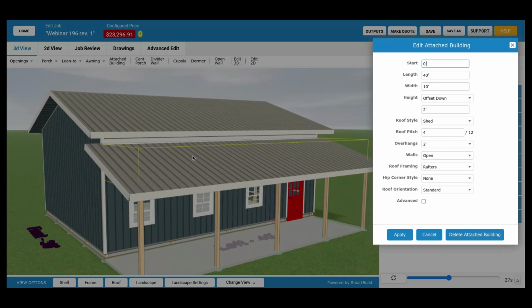because you could potentially have a non-vented gable, right, where you don't hold the sheathing back, so there you'd have an offset of 0, or eave, ridge cap, non-vented ridge cap. But if I use a vented ridge cap, if I use this vented ridge cap, I need it to be held back 2 inches. If I use this other vented ridge cap, I need it held back 4 inches.